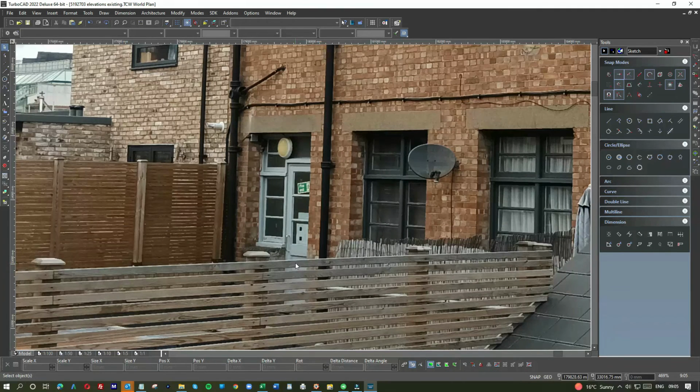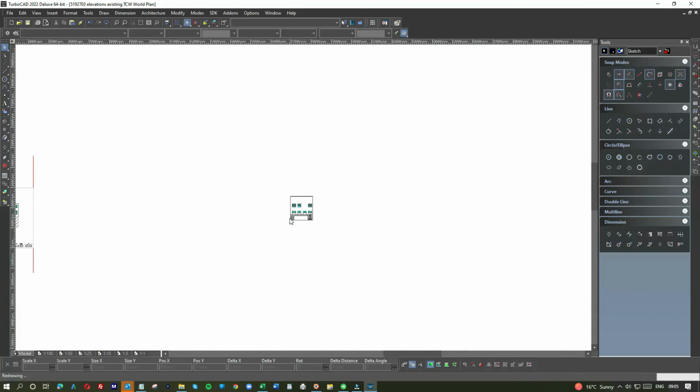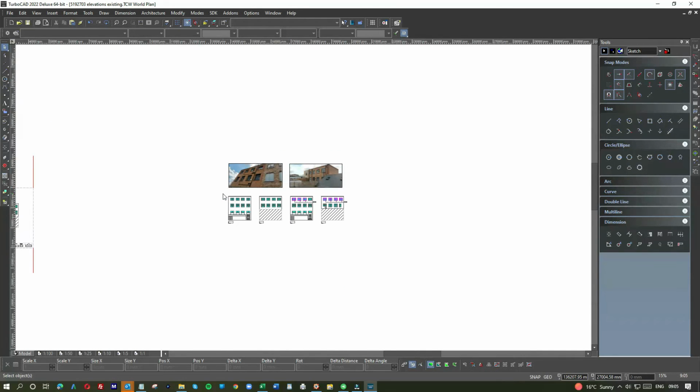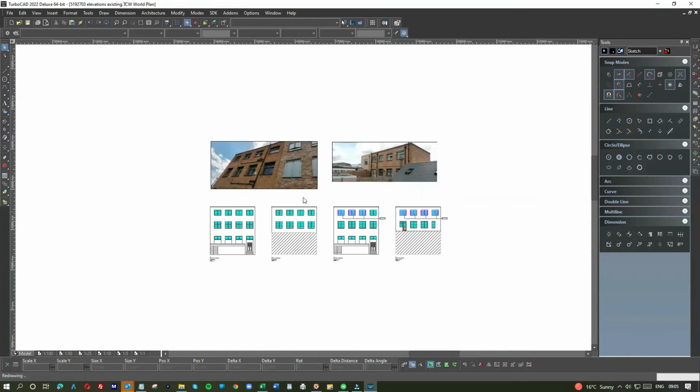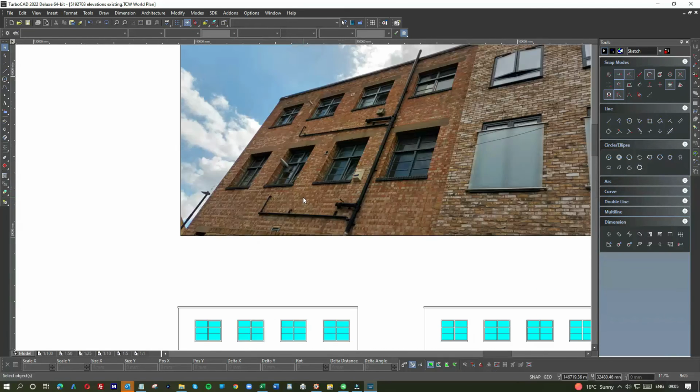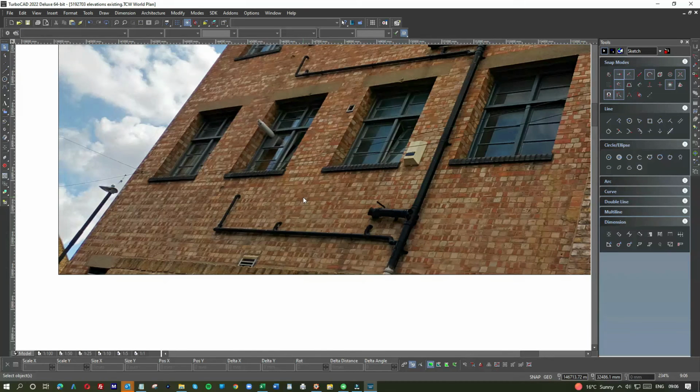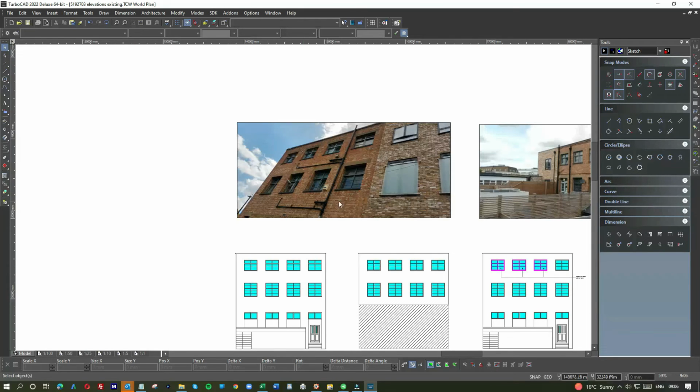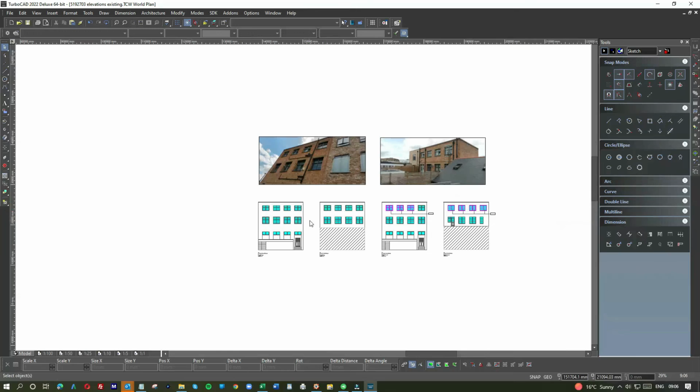Okay, there's not much more I can tell you here, other than you get your photos. A lot of times we can take the photos from Google Street Map, or we ask the client to go and take photos of the elevations, and then we give them a quote over the phone, by email or text. We can do that if it's brickwork, because we can easily measure. An average brick is 225 by 65, and if we want to add mortar, we allow for that as well. So it's very easy to measure up a building using the brickwork. In this case, it's a very simple project.